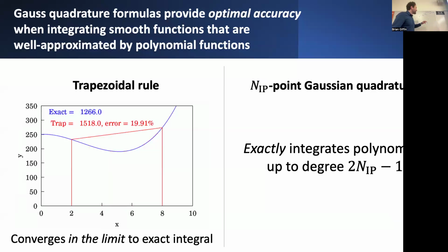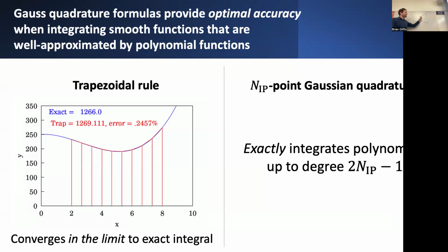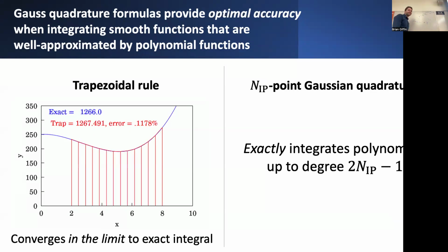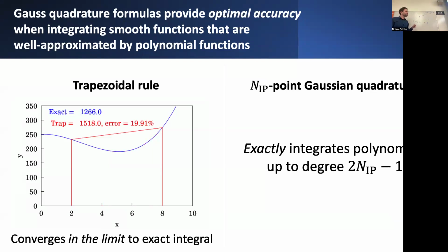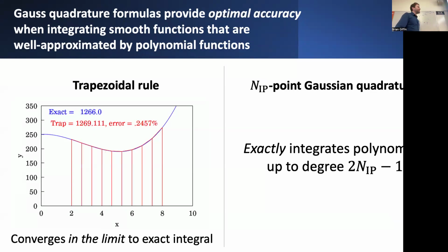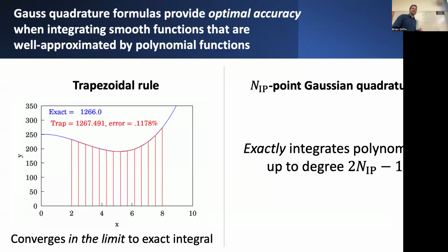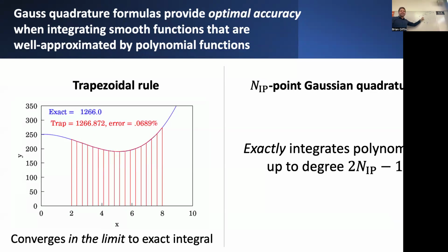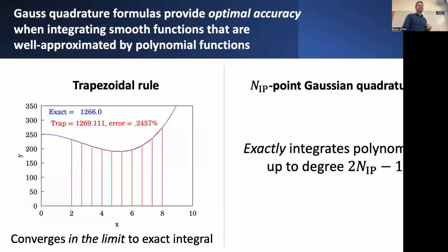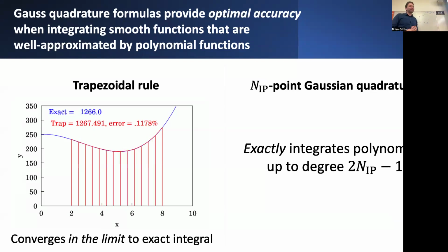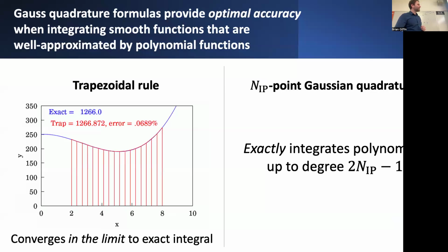If we treat the interpolated representation of the displacement field as some polynomial interpolating function, then I know that the resulting integrals I get in solving the weak form and assembling the finite element stiffness terms will involve integration of polynomials of finite degree, in which case using Gaussian quadrature formulas is really the right solution.